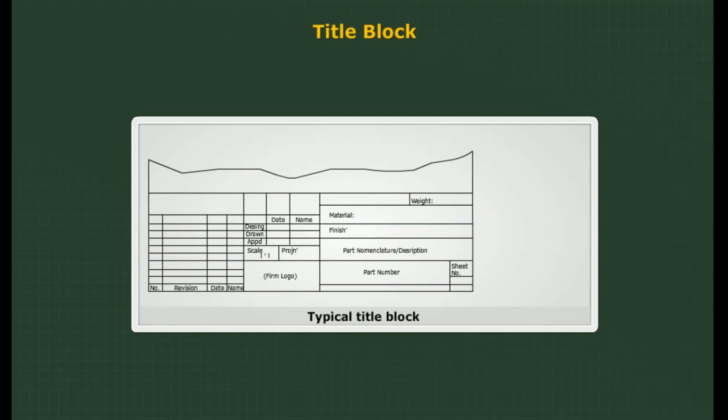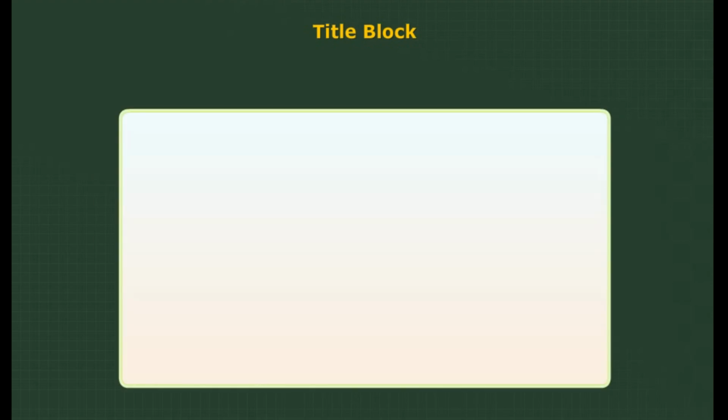Example, clutch spring. Part number, important to assign a distinctive number to track information. Number, arrived at on the basis of some protocol decided by the project group or digital data handling group. Logo, optional if the firm wishes to announce their ownership. Projection, type of projection in notation form or scale of drawing. Revisions or alterations, important to know if one is the latest design or outdated.